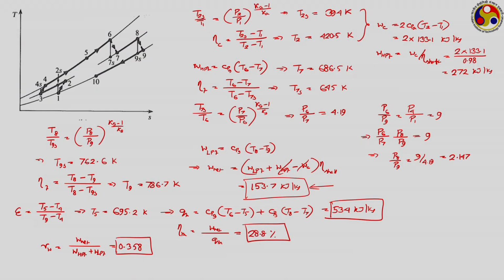So, just use that information, and that is going to give you the mass flow rate equal to 5 megawatt, that is 5 into 10 cube kilowatt, divided by 153.7, which comes to be equal to 32.6 kg per second. This is the way we can solve quite complicated problems with gas turbines also. It is a quite practicable problem.